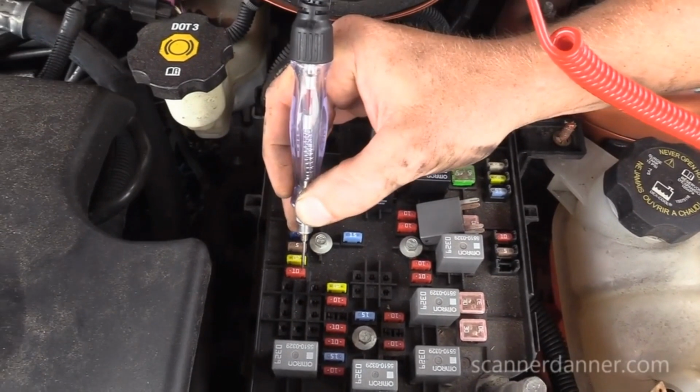Maybe. Could be. Short to ground, though, would do what with voltage? Think about this. Short to ground. Any wire, any component, any circuit, any car, any year. Short to ground. What is the ground on a car? What's the voltage level on a ground on a car? 0. If a wire is shorted to ground, what is your voltage going to be? 0. So it can't be a short to ground. Could be a short to some positive, some wire trace in between, you know, the 2 wires touching each other. Could be that. Could be that.